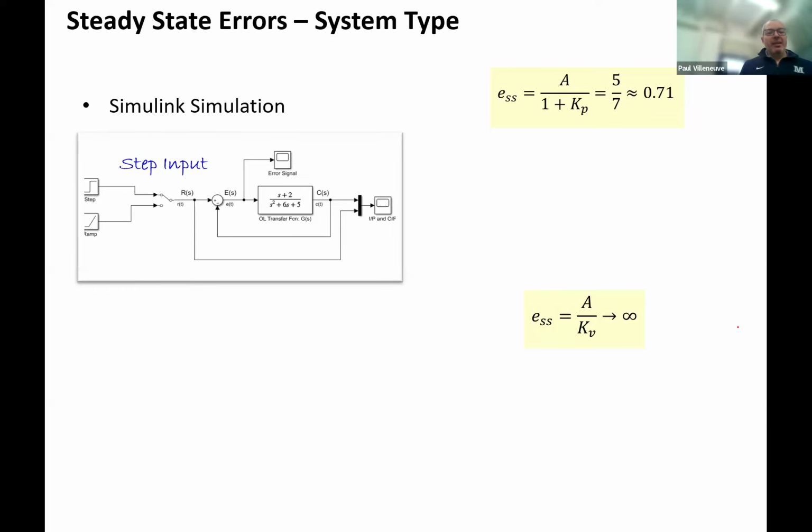But when you do a lab, you build it exactly the same way that you would build any other Simulink model, but you're pulling out your error signal right here. That's all you need to do. Change anything that you've done in Simulink is just bring out the output signal so you can see it. Remember, the Simulink one is going to give you a time domain response, but it's going to give you the full time. It doesn't give you the steady state error until you see it reach quote unquote steady state.